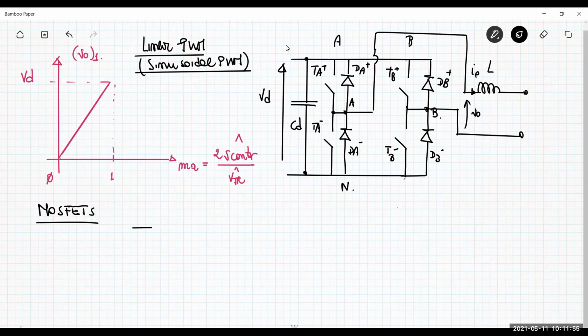it happens that when the MOSFET is on, so when the voltage across its gate and source port is higher than a specific threshold, let's say from 4 to 6 volts typically for a power MOSFET, the transistor conducts current to the drain, but this current can be bidirectional.